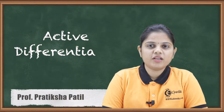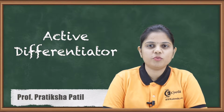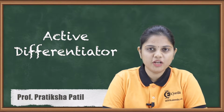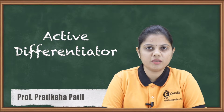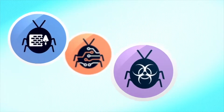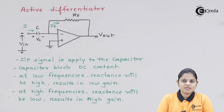Hello friends, in this video we are going to learn active differentiator. In the previous video we have seen the integrator, where the output voltage is proportional to the integration of an input voltage. Whereas here, the name itself is explanatory: active differentiator. Since it is an active differentiator, the element used to design the circuit must be an active element. So we are going to implement this by using an op-amp as an active element. Differentiator means the output voltage will be proportional to the differentiation of the input voltage.